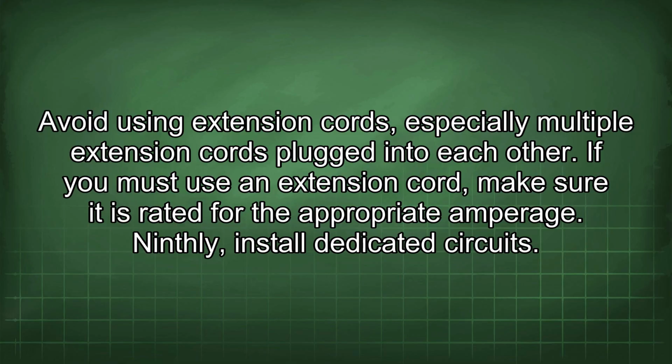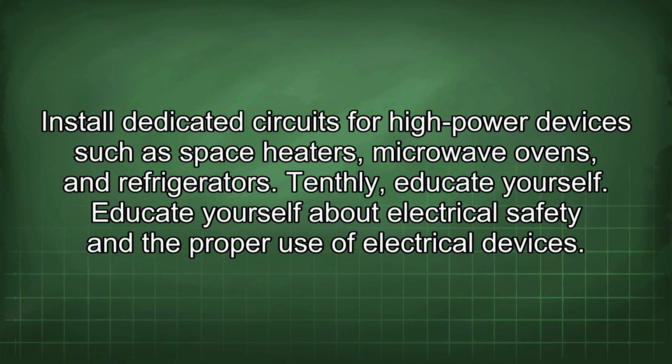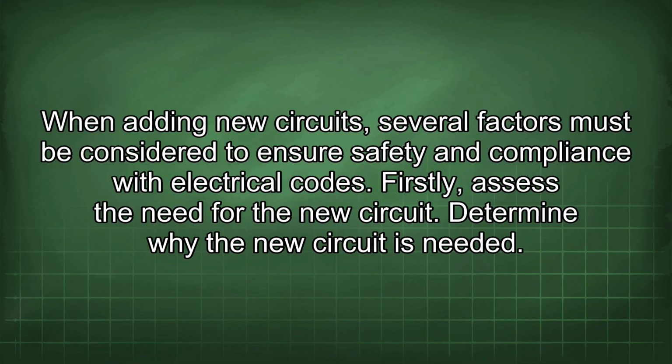Ninthly, install dedicated circuits. Install dedicated circuits for high-power devices such as space heaters, microwave ovens, and refrigerators. Tenthly, educate yourself. Educate yourself about electrical safety and the proper use of electrical devices. When adding new circuits, several factors must be considered to ensure safety and compliance with electrical codes.